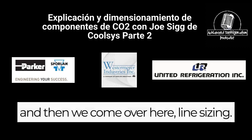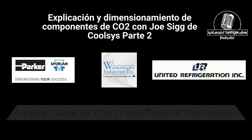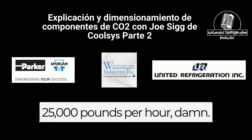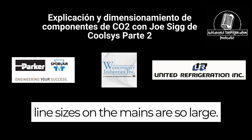Then we come over here to line sizing, and you can see we've already done this, but look at the mass flow of the system: 24,000 pounds per hour, 25,000 pounds per hour. That will tell you right there why our line sizes on the mains are so large.